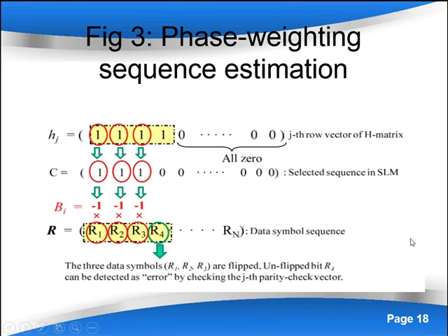To decode the received data, we need to estimate whether each weight factor is 0 or 1. In the proposed method, weight factors are estimated by a sum product decoder, which offers not only error correction capability but also weight factor estimation.